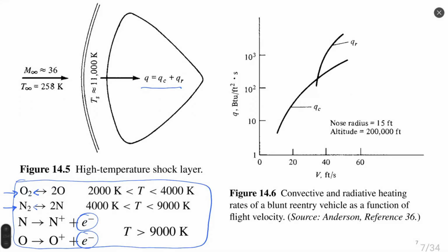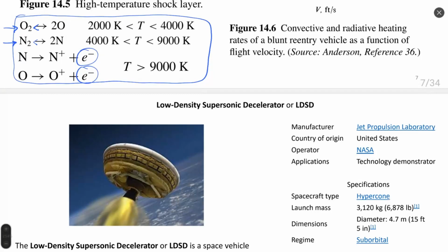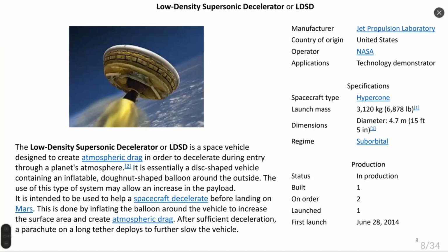Okay, the model of hypersonic flow has this chemical part. When I ask you what is different between hypersonic and supersonic flow, do not forget to tell that dissociation and recombination and ionization of gas may happen, and we must take into account these processes. How much it's different, we will see very soon in one example. You will see that consumption by these chemical processes can be around 80% of total energy, so it's a huge difference.